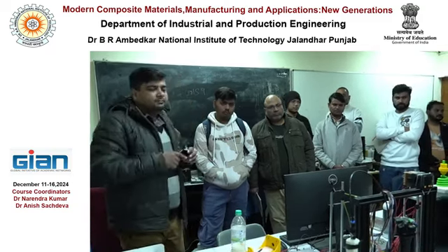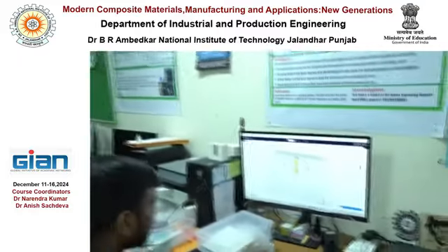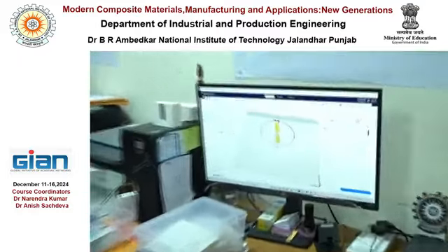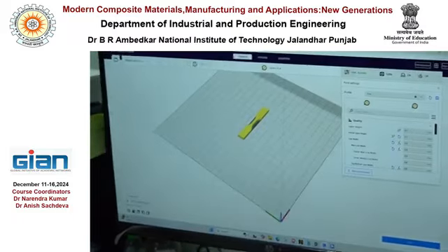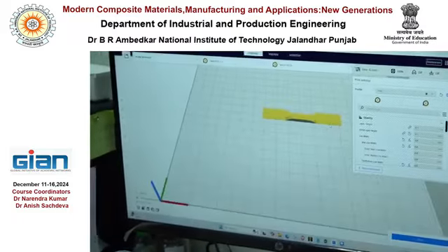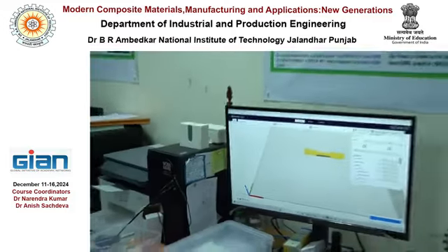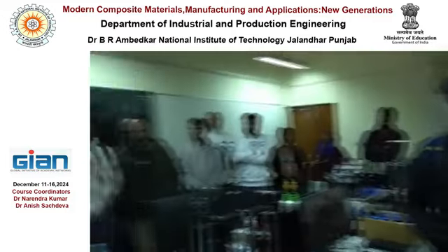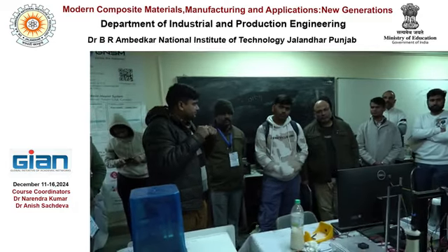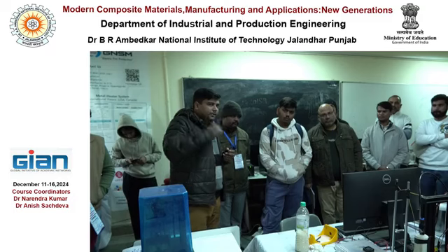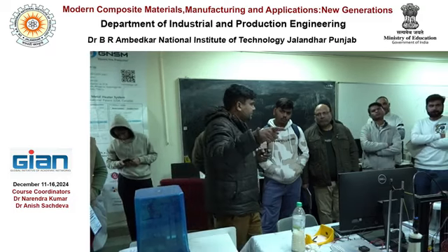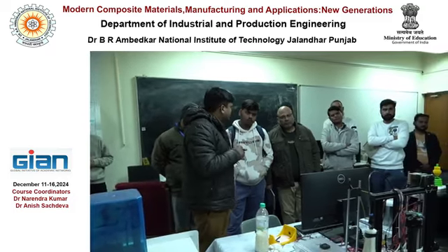Okay, just flip it again to the same condition. So again here, change the orientation to 0 degrees. Orientation is the position of the specimen with respect to 3D space, with respect to the build volume, right? So now again the orientation is in the XY direction.